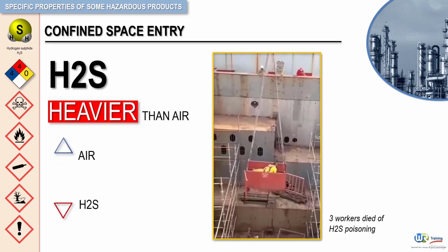This tragic accident could have been avoided. The lack of compliance to the site procedure was a key factor in this incident. Now, because of the dangers involved in entering confined spaces, only those employees trained and authorized may enter a confined space. Your company should and must maintain a written confined space entry program that details the safe work practices required to enter each confined space and establishes a written permit entry system to ensure that all hazards have been controlled.